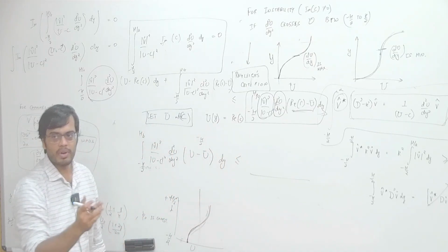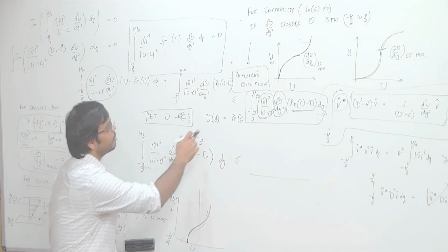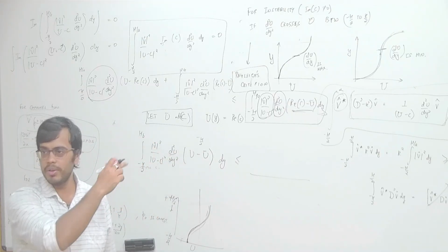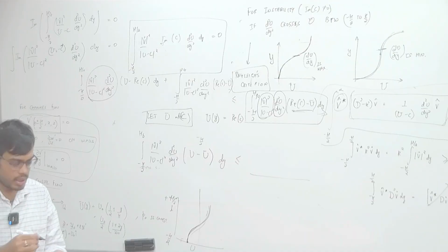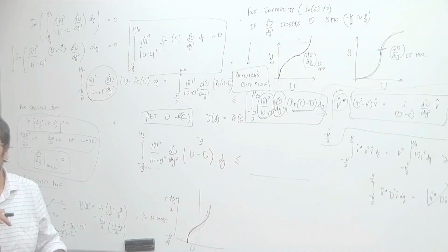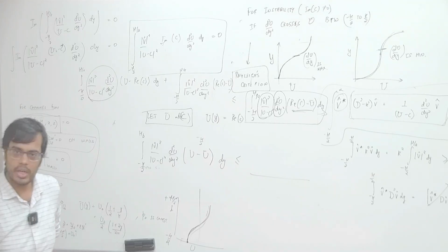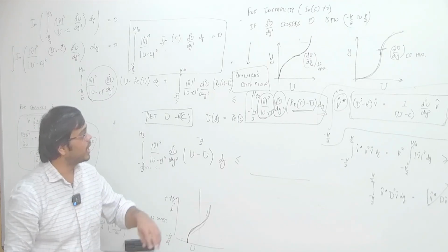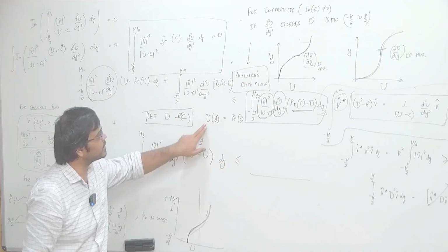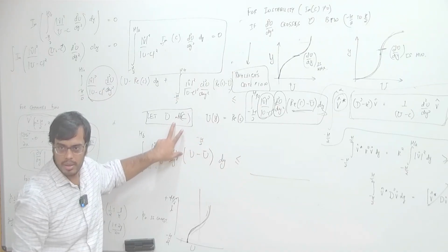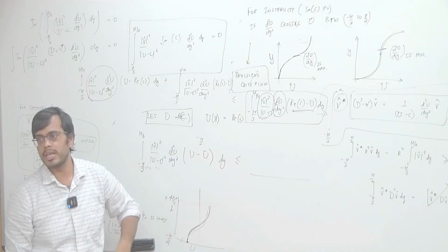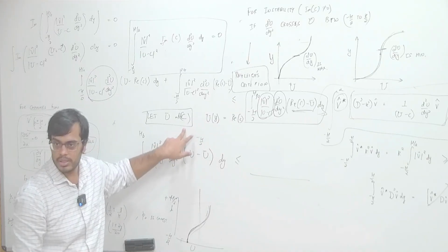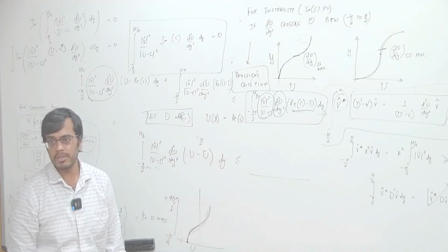If you have a y location where your capital U is equal to c, then notice what I discussed in our previous section, that you can transform the frame to some value of capital U and look at the perturbations in that frame. In a frame that is traveling with the u bar velocity, the perturbations will be stationary.